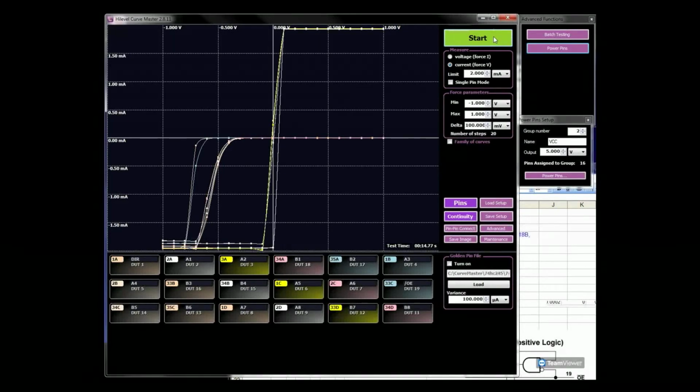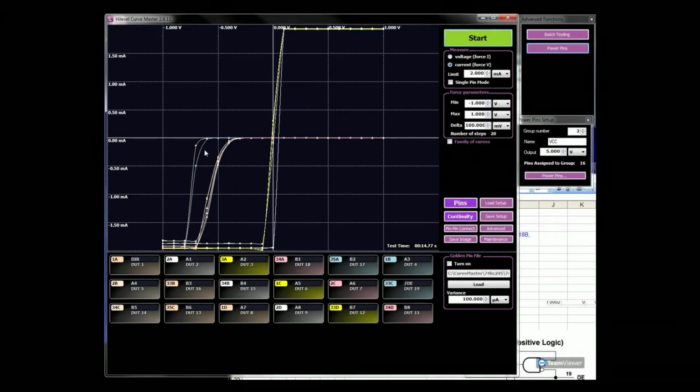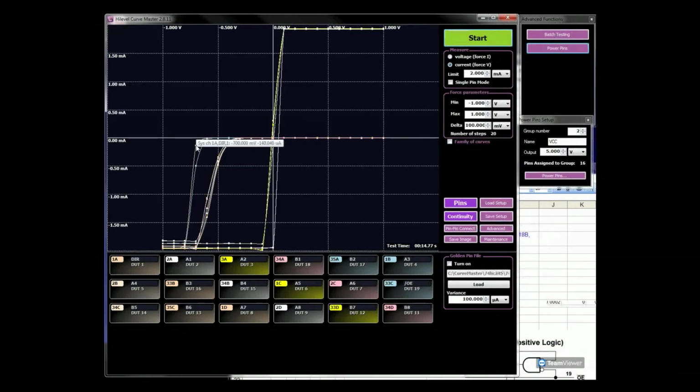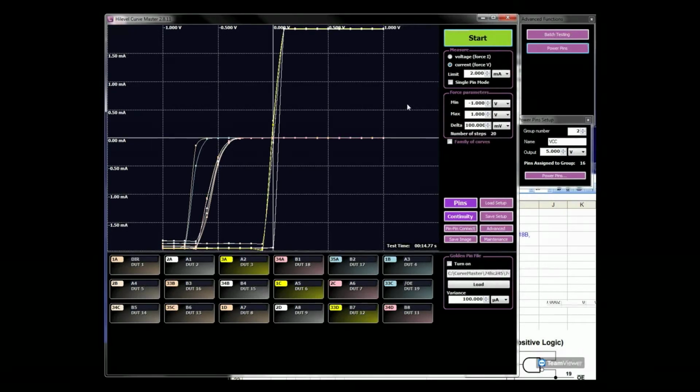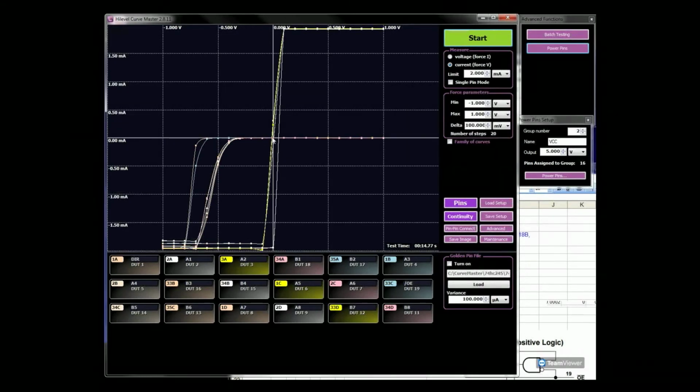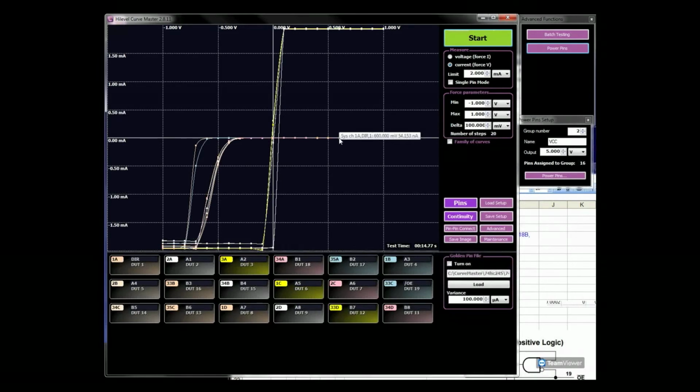Does this mean the plot is not real? No, it is as real as the other plot. Simply by putting 5 volts on the power pin, we trace the curve of the pins while the device is powered. Notice that DIR and the output enable no longer go to the same voltage. They stop at 0 volts. Why? Because we move the reference point for the upper diode to 5 volts. We never reach a point where this diode is enabled.